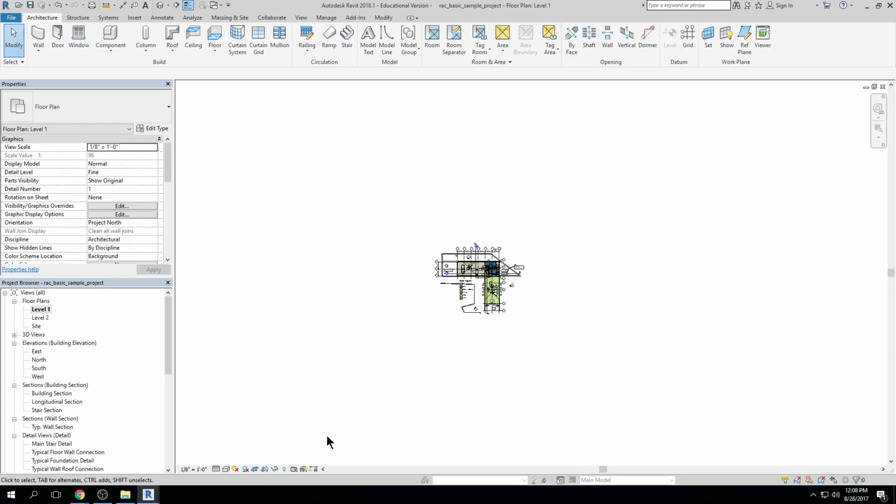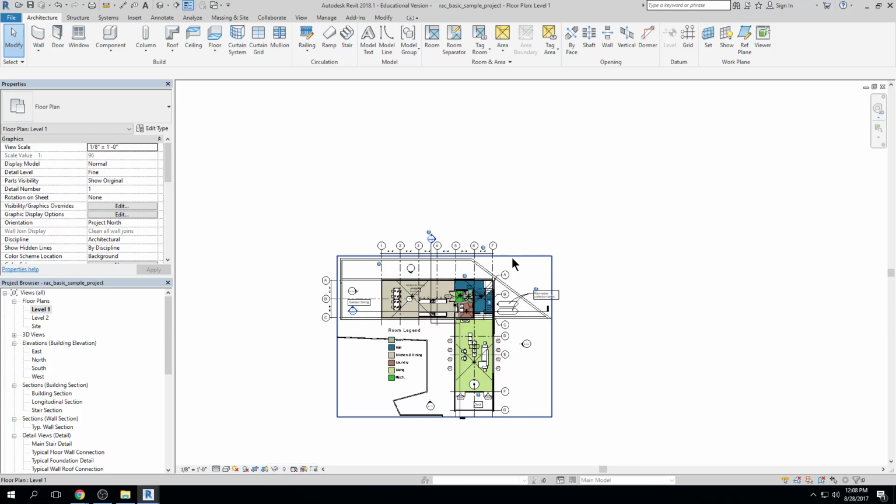So I can click and it shows items, but how do I define that boundary? Well, right next door to that little guy, and I honestly don't know why these are so tiny, I feel like I'm squinting constantly. If I click on that, you see the little light bulb pops up. That will reveal and hide the crop boundary. So this is my crop boundary.